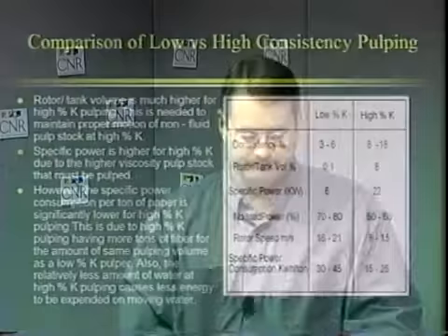impacting the fibers and the paper and breaking it up. So the rotor tip has to move very fast. That rotor tip has to hit the paper really fast to break it. In comparison, the high consistency pulper is just gently moving that pulp around, and where the rubbing and the breaking is occurring is when the pulp is rubbing against itself. So it can go more slowly.